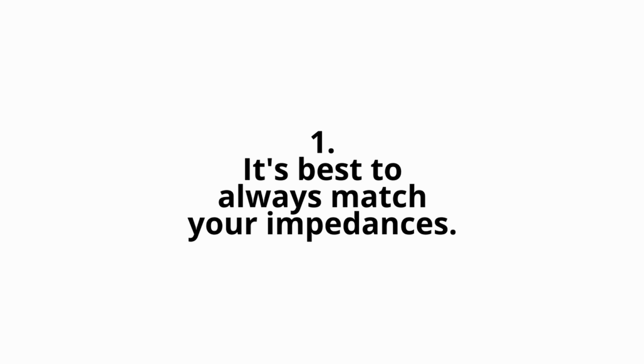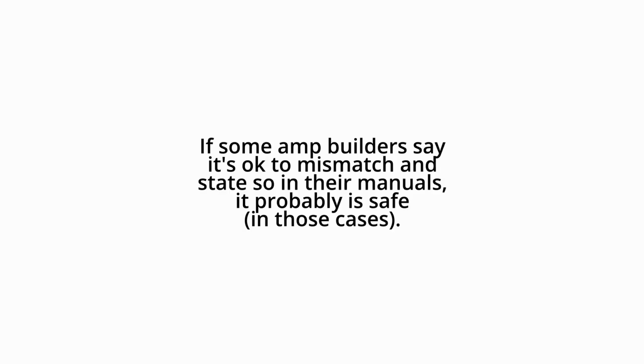Always match your impedances. But if you, for some odd reason, don't want to, refer to the manual, or even better, ask the manufacturer what is safe and what is not. On a side note here, some manufacturers do even recommend experimenting with mismatches in their manuals, so mismatching is not always so dangerous. But again, if you don't know or haven't read the manual, it's better to play it safe.